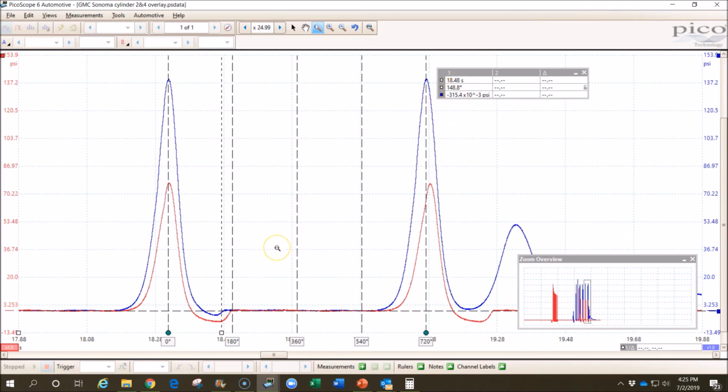So right there is an indication of our problem. We have an exhaust valve on this cylinder that's opening later. Now we're off just a little bit here and we're off here, but that still is not enough to affect this. They should be exactly on top of each other, so we can see that we clearly have a delayed exhaust valve opening. So maybe a worn camshaft lobe or something along those lines on that cylinder.